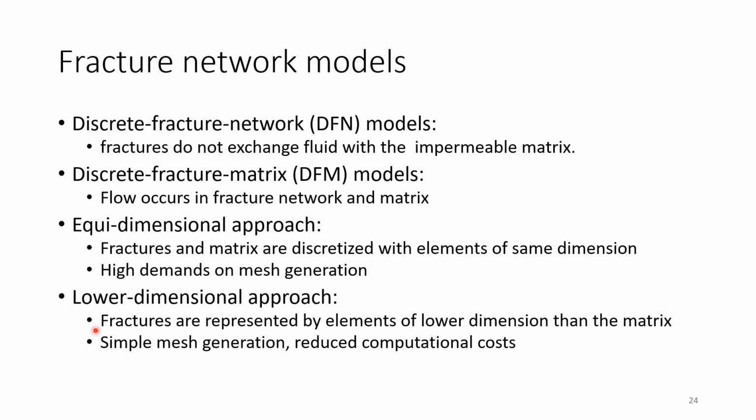But you can also neglect doing this or avoid doing this. So you represent the fractures as they are in full 3D. But of course, this gives you high demands on spatial resolution or mesh generation, because if you have very thin faults or fractures, to discretize those with a full grid means you will have very, very small mesh elements, which then increases your mesh generation effort but also your computational cost.